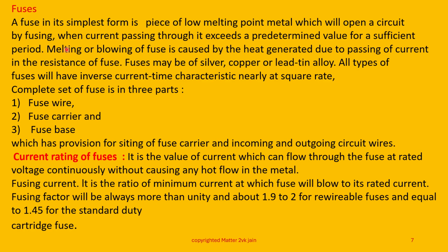Melting or blowing of fuse is caused by the heat generated due to passing of current in the resistance of the fuse. Fuses may be of silver, copper, or lead tin alloy. All type of fuses will have inverse current time characteristic nearly at square rate.